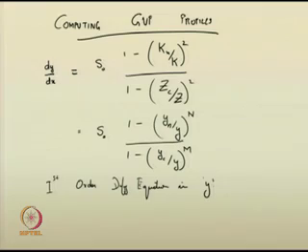So, based on one control section, one can easily start the profile computations. Solving this differential equation means you can identify the distance from the control section for a particular depth of flow, or for a given distance from the control section, what the depth of the water profile could be.